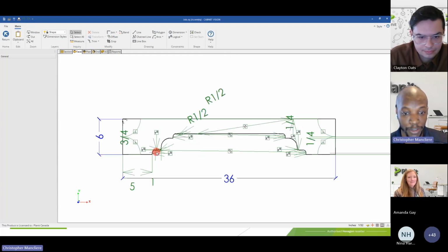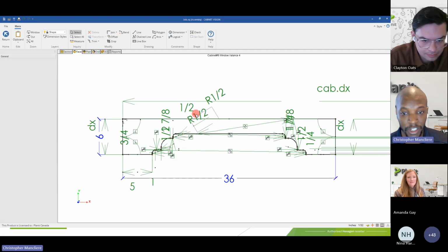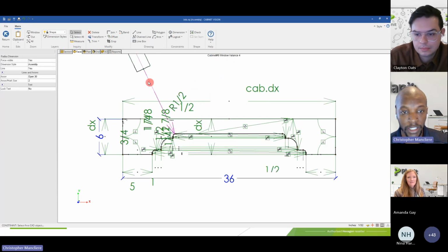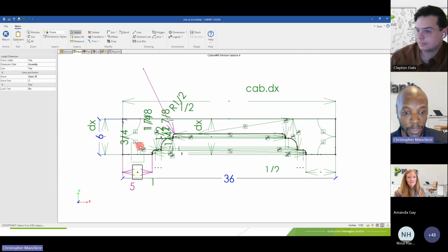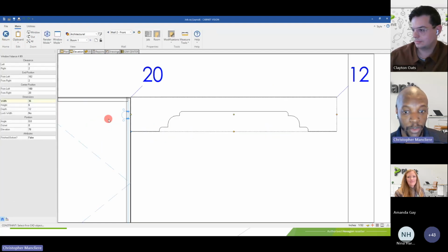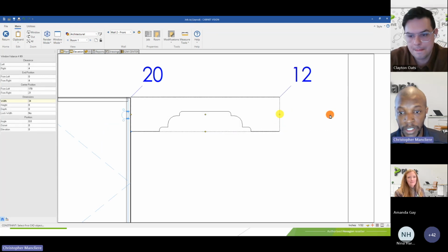But if you see that there are so many constraints that you're having trouble, it's starting to overlap, keep in mind that you can select any constraint that you add and after that move it freely around the geometry. Just because you put it on a line doesn't mean it has to stay there. It will still be attached to this segment, but you can move it so it's not in the way. You can reselect it and get to the geometry you want in the drawing. Once it's created, it will just disappear, but you can reorganize those on the screen if needed, and then you can still use your part freely.